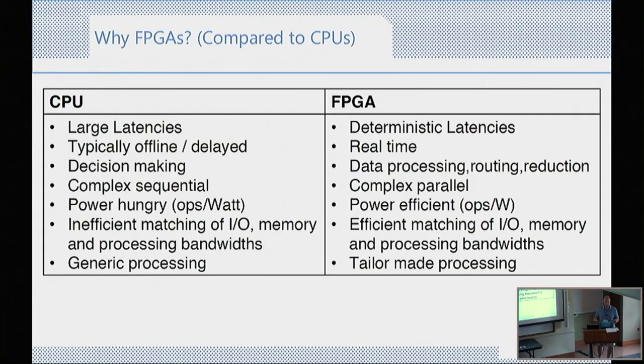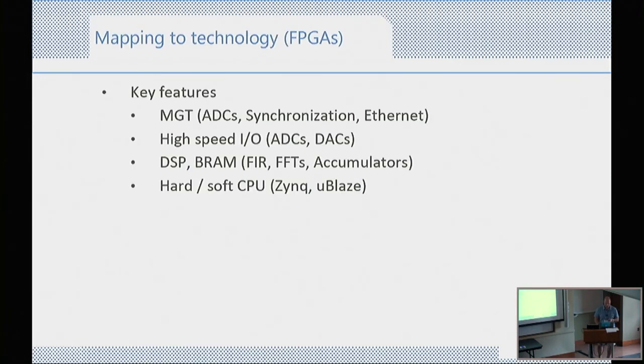FPGA is also very good. It's got a good match between its I/O, its memory, and its processing bandwidths, and you can tailor it. It's also power efficient, and as I said, the operational budget gets affected by that. The key features that we like about FPGAs are its multi-gigabit transceivers for the interface, high-speed IOs, DSP, and DRAMs. It's well suited for FIR filters and FFTs, and then we can also have hard and soft CPUs in terms of Zynq and MicroBlaze.